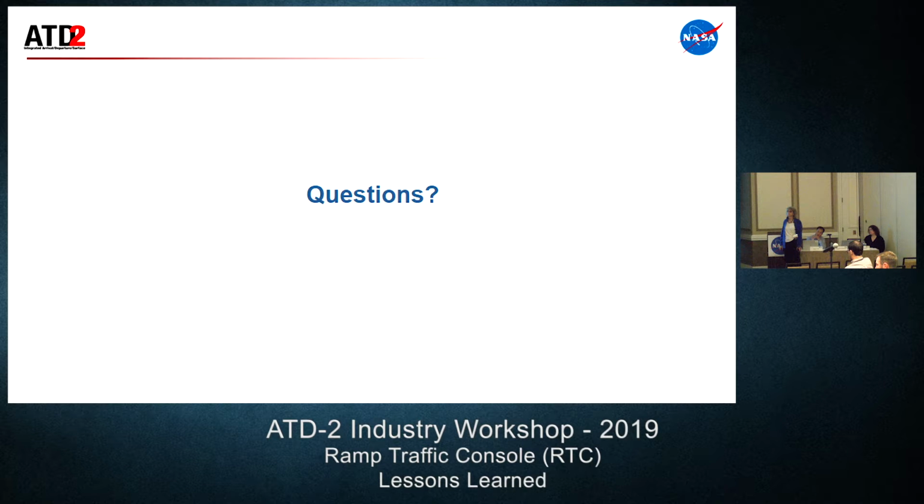Is there some kind of policy in place that makes sure that the airport has some kind of surveillance capability all the way to the gate, i.e. a multilateration system, or is the FAA planning to make the ASDE-X system not filter out the alley so that the users can have the surface surveillance all the way to the gate?